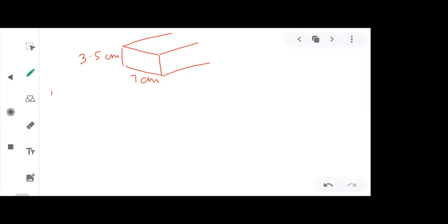First, I will go for frequency, but see, cutoff frequency you cannot find out unless the mode is disclosed to you, like whether you're asked to find out cutoff frequency for TE mode or for TM mode. If nothing is mentioned, you go for the dominant mode only. Remember this. If nothing is mentioned, you consider that you are going to calculate cutoff frequency for the dominant mode, because generally waveguides are operated for the dominant mode only.